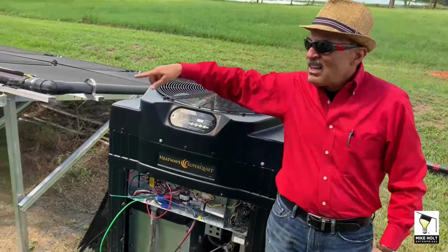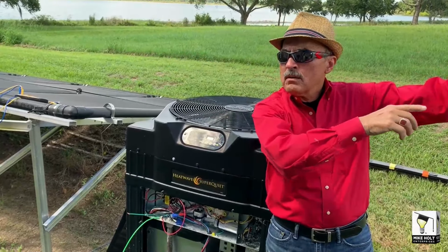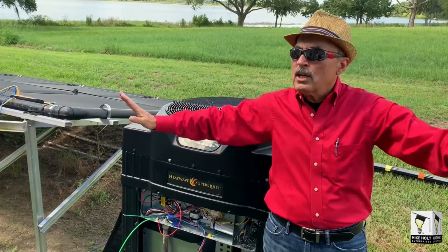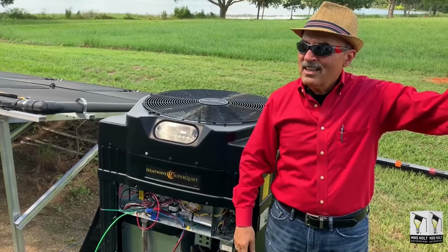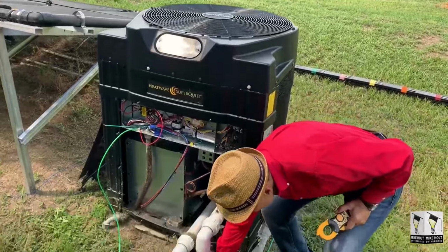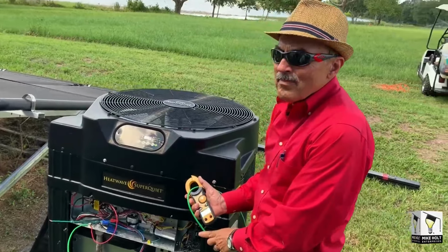We had a conductive wire, copper or aluminum, running all the way back to the transformer. That was the effective ground fault current path. Properly installed, properly terminated, right? It'll clear it. You really think the dirt is going to be a conductor? Because look at it. It was less than 1 amp.